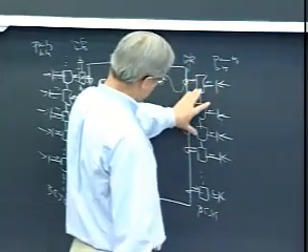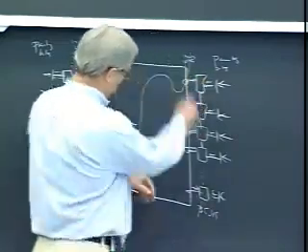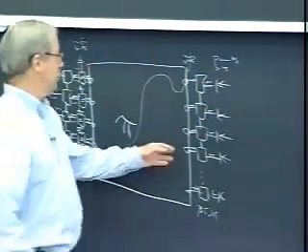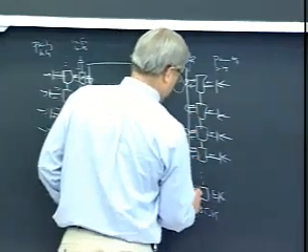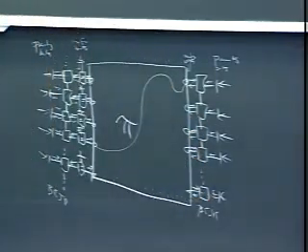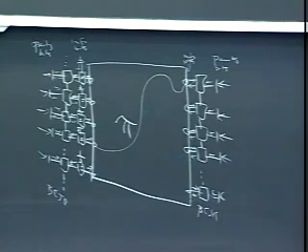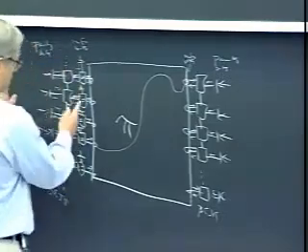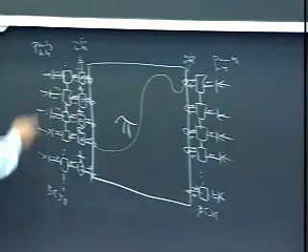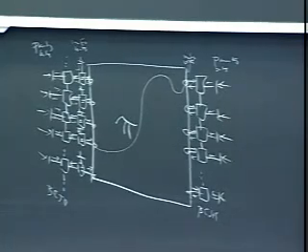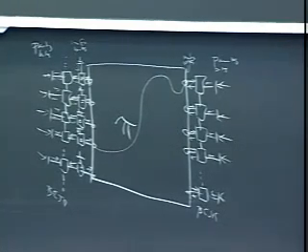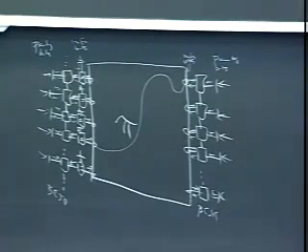It works just fine. You come over here, you then do a complete sweep through 1,000 bits or whatever, and you develop outgoing messages here, which again, let's hope we've improved the signal-noise ratio a little bit more, that these are even more informative about the input bits. And they come back, and now with this further improved information, we can sweep through here again. That's where the turbo comes from. You keep recycling the information from left to right, from right to left, and hopefully you build up power, you lower the signal-noise ratio each time.